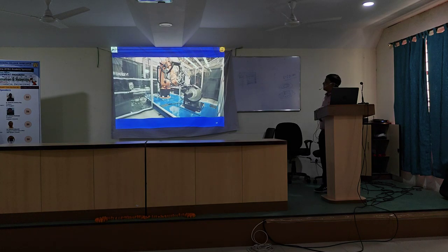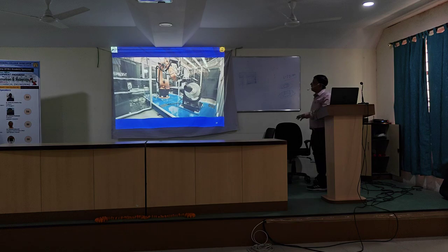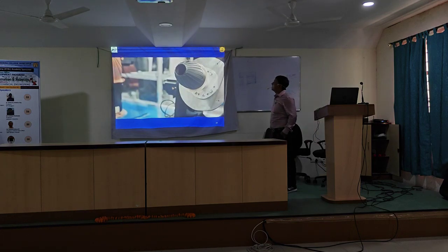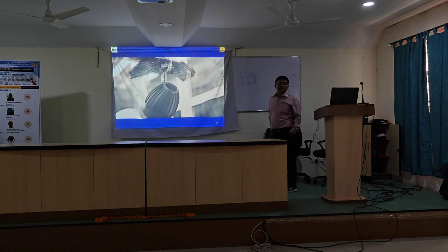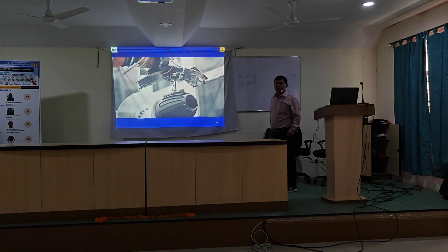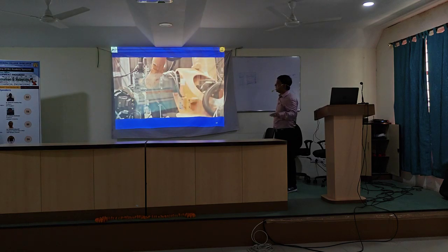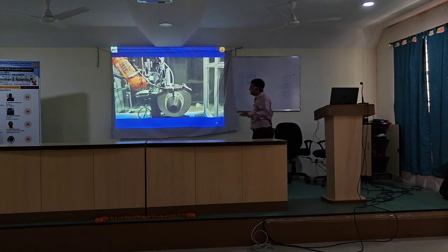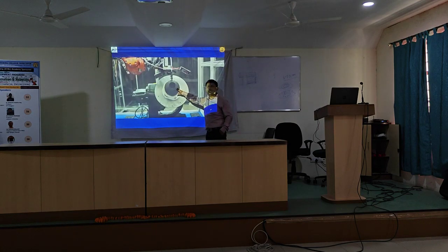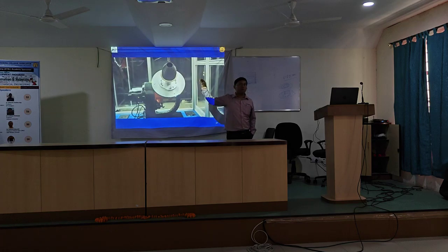See the robotic printing, but obviously here the slicing is different. No traditional slicing will be used in this case. That is for the Cartesian 3D printing system, where slicing is done. Here the slicing is different. This slicing is called conformal slicing.